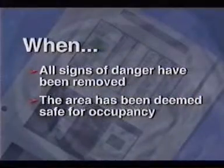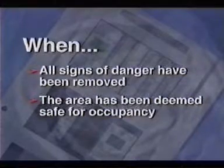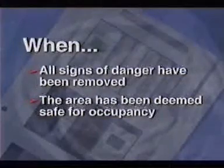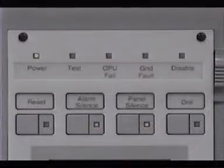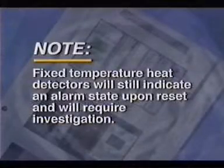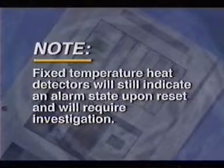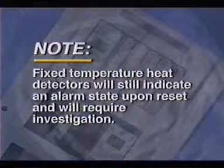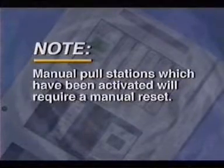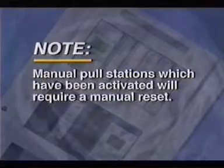When all signs of danger have been removed and the area deemed safe for occupancy, the fire department authority on scene will restore the panel to normal operation by pressing the reset switch. Note, fixed temperature heat detectors will still indicate an alarm state upon reset and will require investigation. Additionally, manual pull stations which have been activated will require a manual reset.